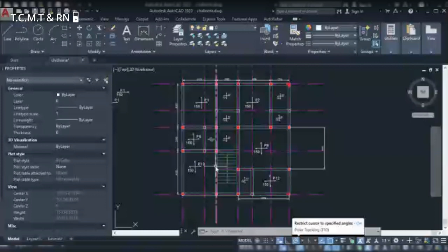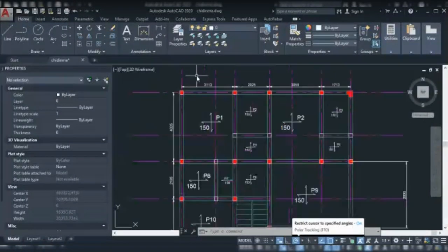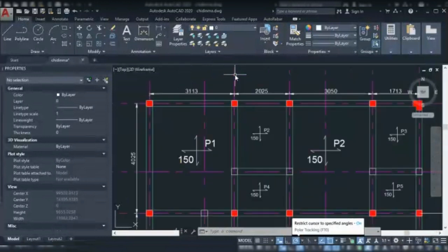Most engineers use 450 mm as the depth of the beam. But in Nigeria, they said the minimum depth of your beam should be 400. Most people use 450 to be on the safer side. So let's now get the size, or the initial depth, of our beam.